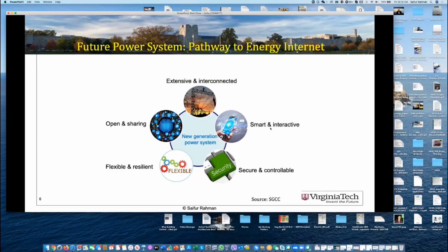What I mean by controllable is happening in the US today. In some cases, rooftop solar, California especially, mid-morning, produces more electricity than the house can use. So they push it to the local distribution network. As a result, because of excess capacity pushed into the grid, the voltage goes up. That means it is not acceptable. In the US, we can allow plus or minus 5% voltage fluctuation. So the power company tries to control those inverters, turning them off as a possibility.